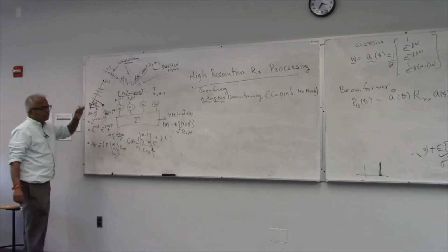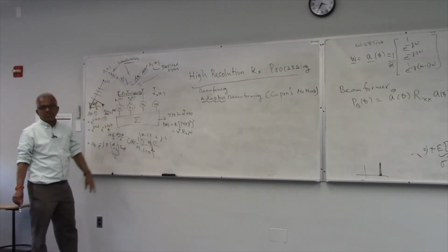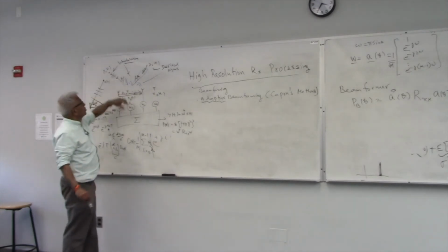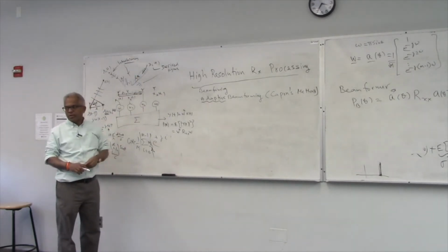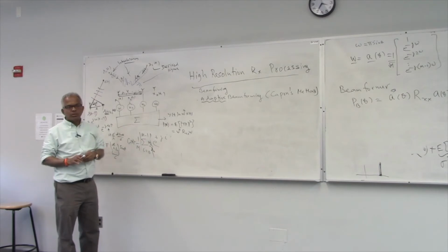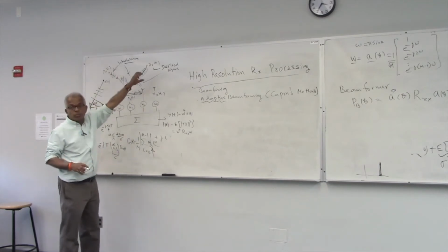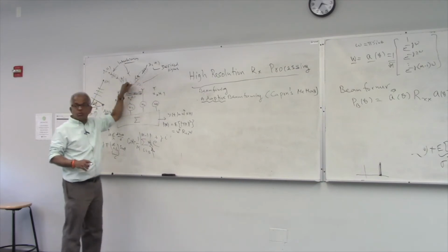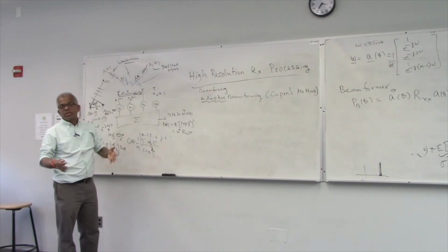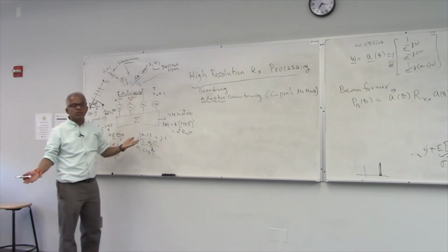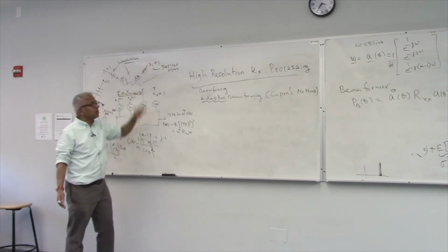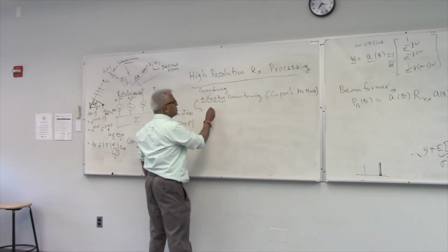So in the adaptive case, this is still true. If you're using weight vectors, this is the output. If you have the desired signal coming in and you also have other things coming in, you have a lot of power coming in. So we want to keep the output as low as possible. That's the strategy, because if you keep the output power as low as possible, hopefully the unwanted signal contributions will be minimized. But you have to do it under a constraint, because if you just say I want to minimize the output, then the best choice is to put the weight vector equal to 0. So we maintain the gain along this direction to be constant.